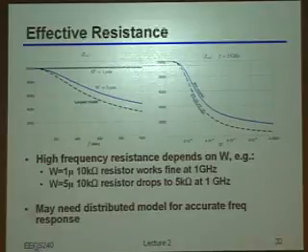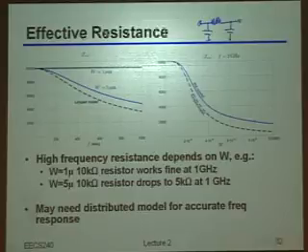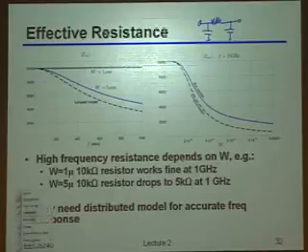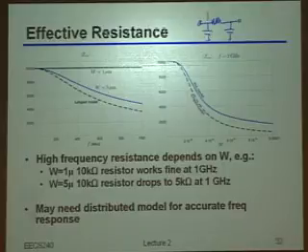So let's go back to our example of a resistor. But this time, let's say that, as a simple model, anytime you draw a resistance, it's also going to have some capacitance associated with it. As we said last time, if this is the case, then obviously beyond some frequency, I won't really get the impedance I wanted from that resistor. Instead, my impedance will be dominated by this capacitor.